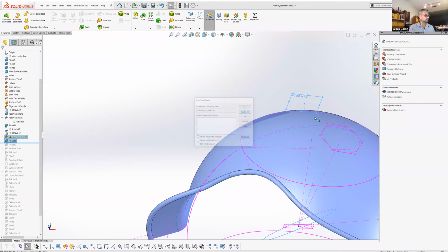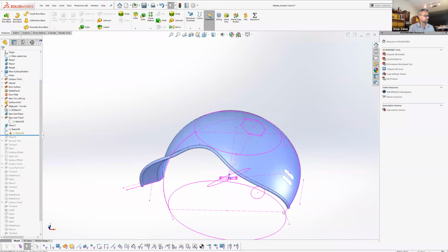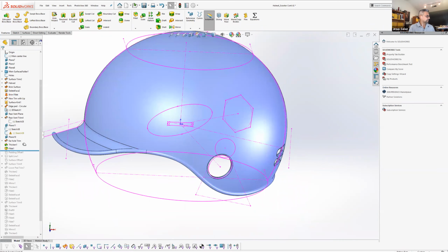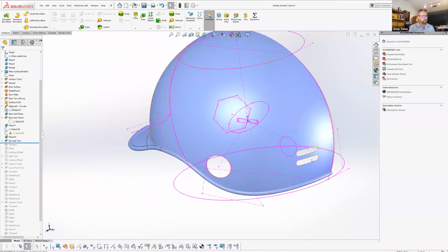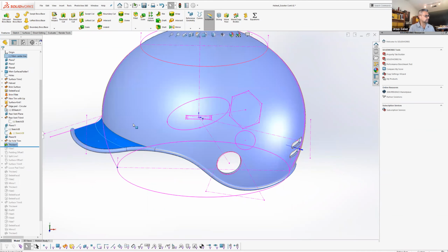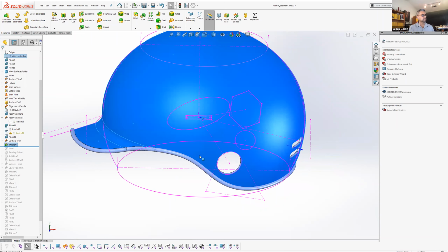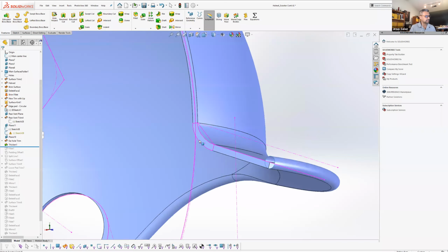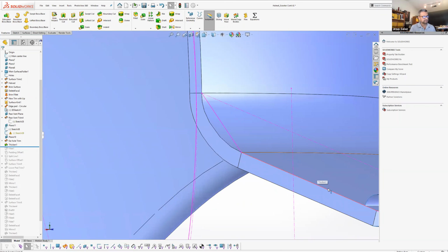Go back to the trims. So as I created some of these, let's see, I'll keep going down. After a couple of these trims, so just a hole for the ear, rear vents, I thickened this surface. So all this was knit, these 3 elements here, actually 4, they're all knit. So I was able to thicken all this all at once.